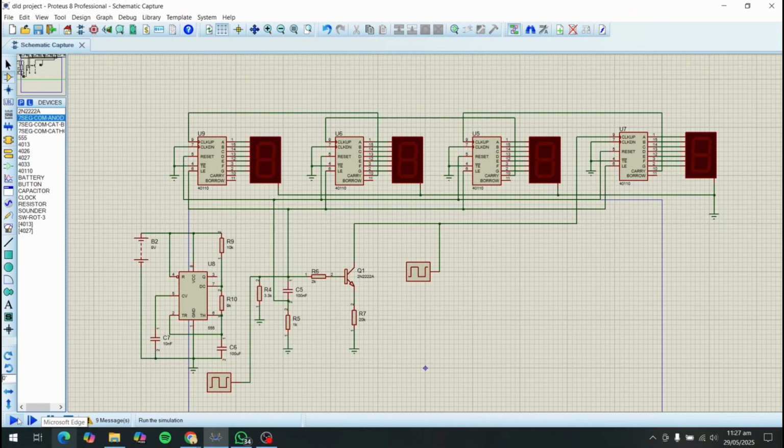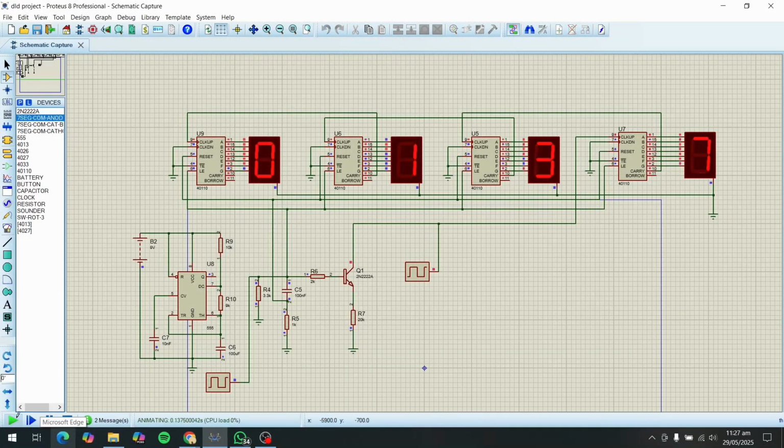The basic working principle behind this is that the counters increment when a rising edge is observed in the input signal. And using a clock, we reset these counters after 1 second, giving us the frequency, or the number of waves passed in 1 second. Okay, so now we will run the simulation using a signal generator as our clock set to 1 Hz. As you can observe, the counter counts towards 1000 and then resets.